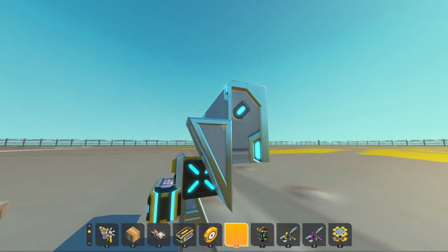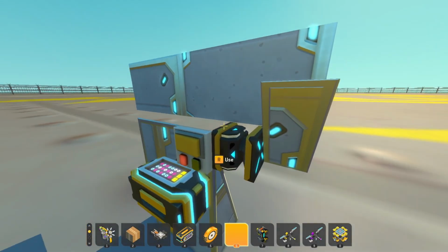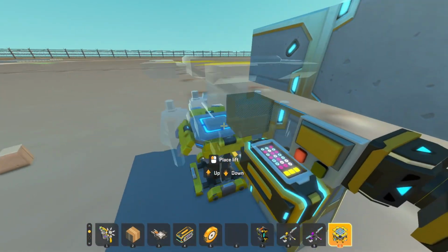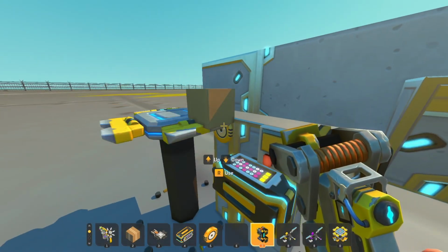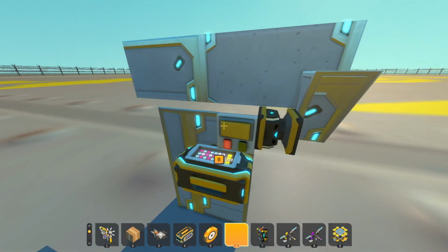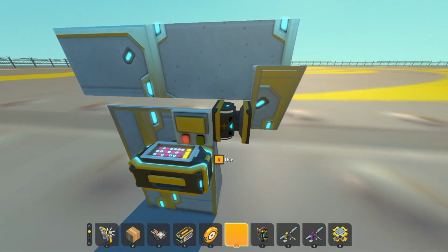So if the child object of the piston were to be compressed backwards, if you were to put pressure up against the piston to push it back, you would now be running into the primary retaining force of the joint, but you would no longer have this dampening effect. Or at least this dampening effect would only kick in once it exceeds some speed. And if you give it a target speed that is essentially infinite, then that dampening effect will never kick in.